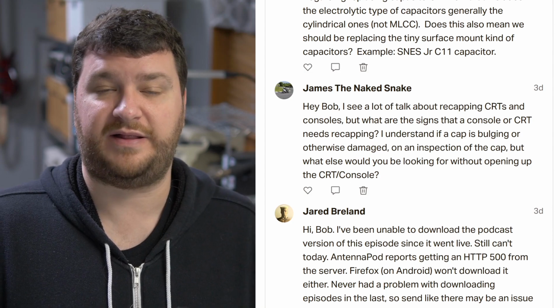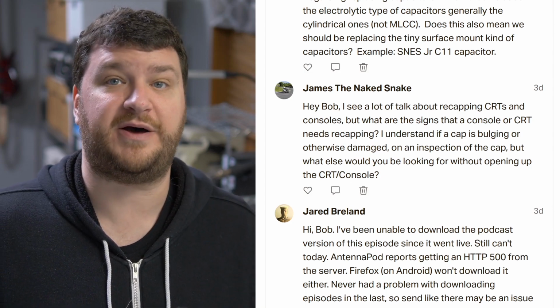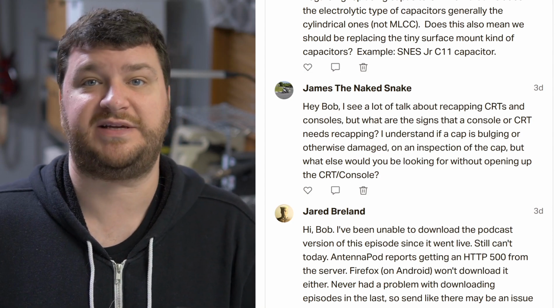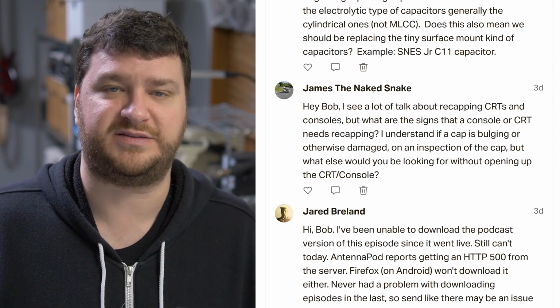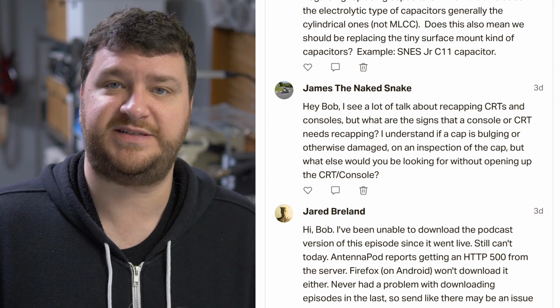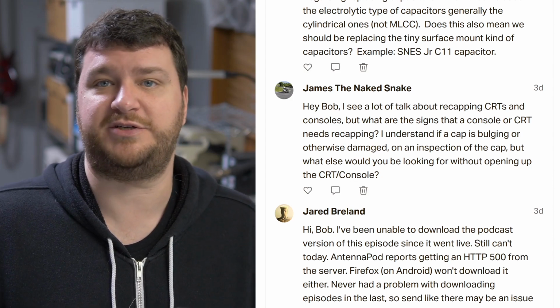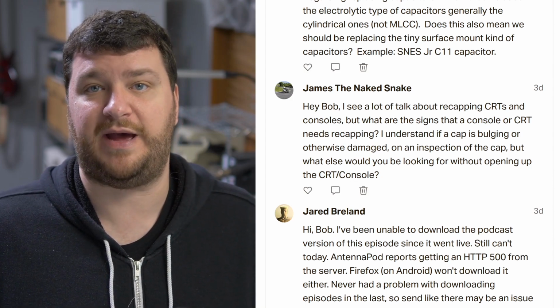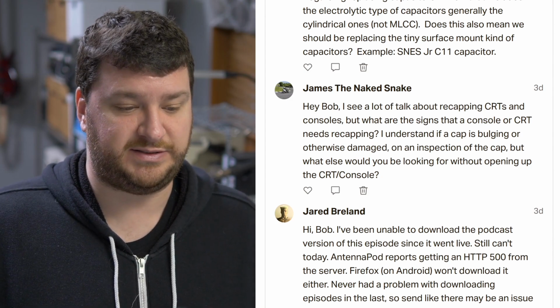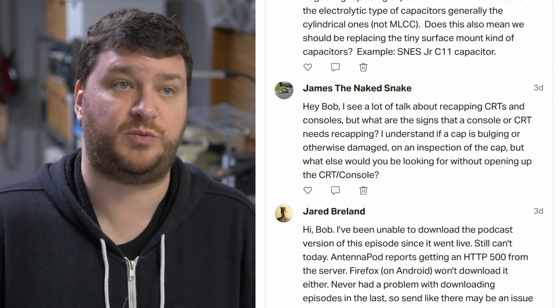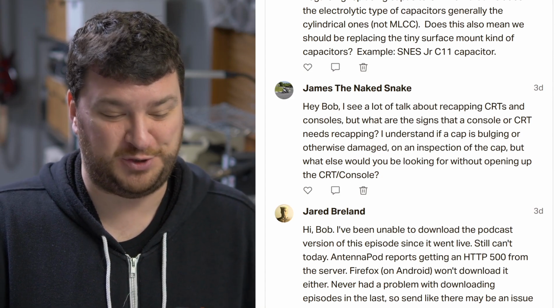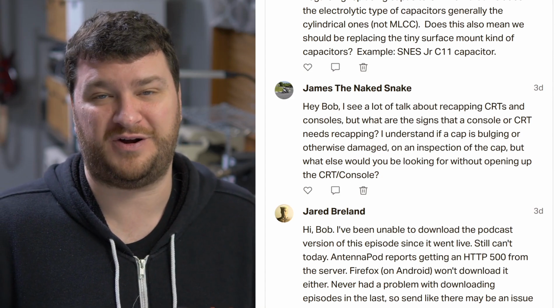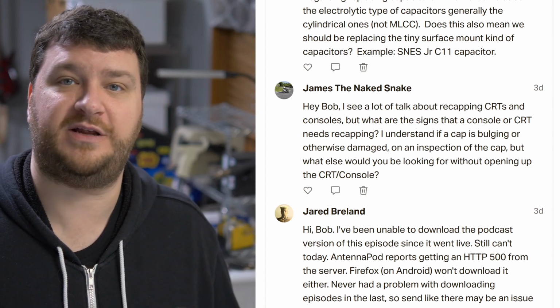But a lot of modders get Turbo Express, Game Gear, PC Engine, TurboGrafx or Turbo Duo consoles from people that say, hey, I'd like you to install a region mod, a new screen, and could you recap it? And they get the console, the modder tests it, everything is working perfectly fine, and then they pop it open, and it is a horror show of leaking caps all over the motherboard. So visual inspection has got to be number one.